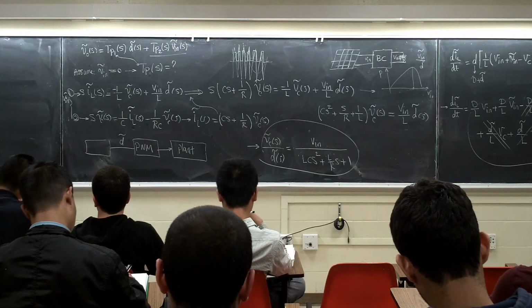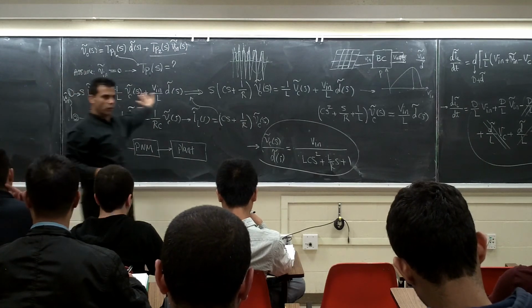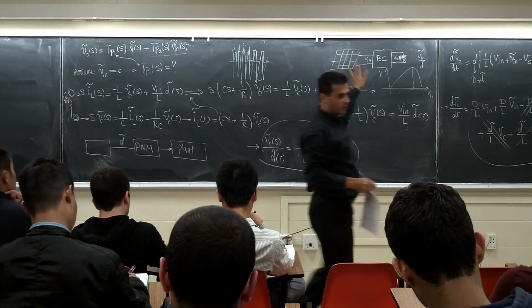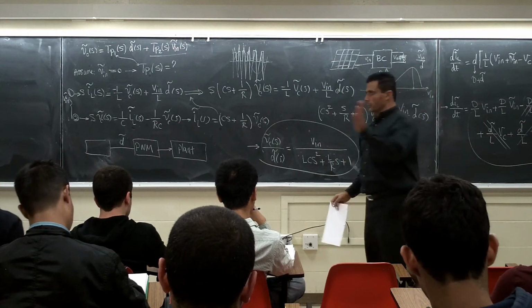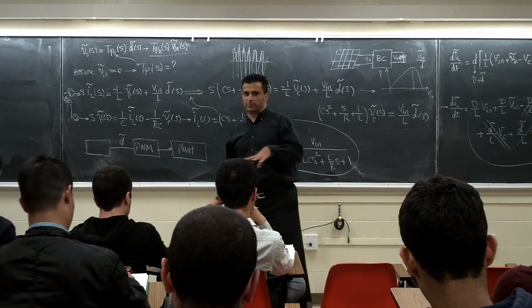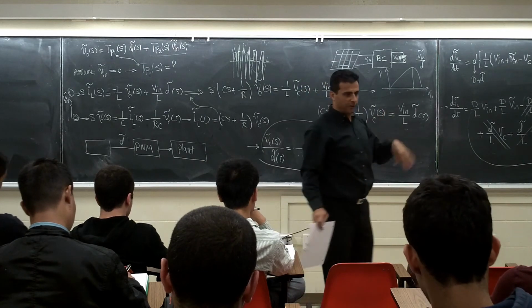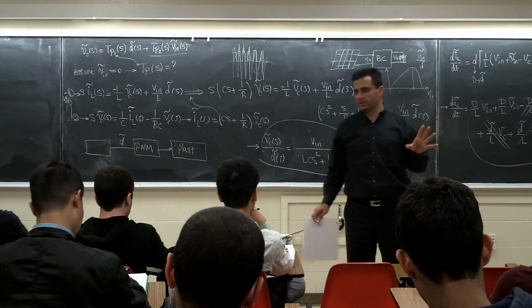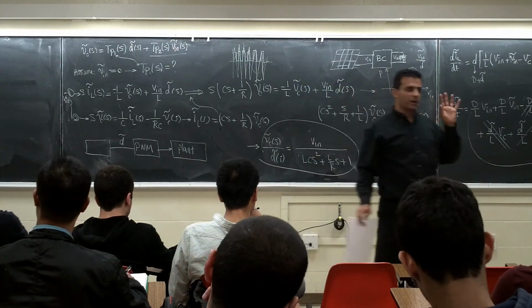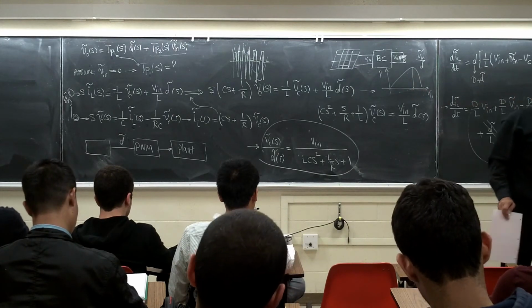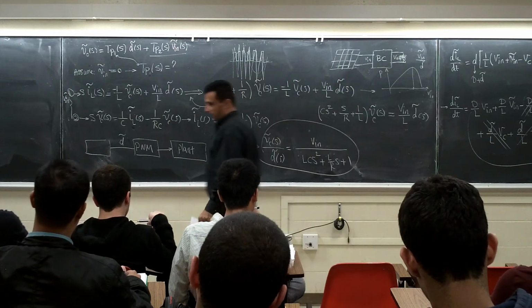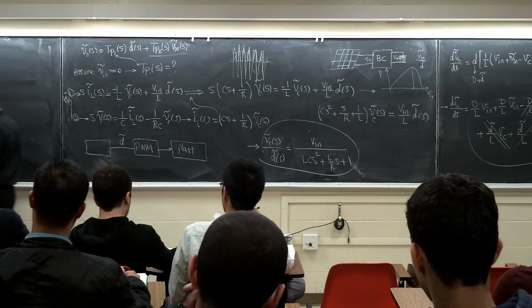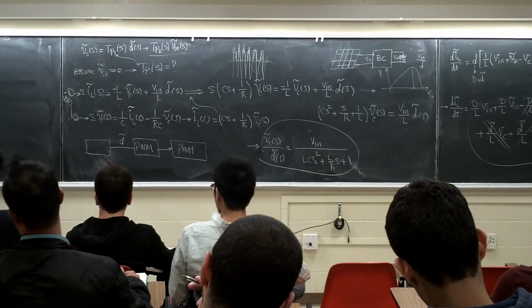What you should do: switch open, switch close, switch open, two sets of equations, right? And you replace the V in with V in plus V tilde, VO with V, VC with VC plus VC tilde, D equal to D plus D tilde, all those parameters, IL the same thing. So I'm not going to write all those things here. You guys are going to do all those equations.